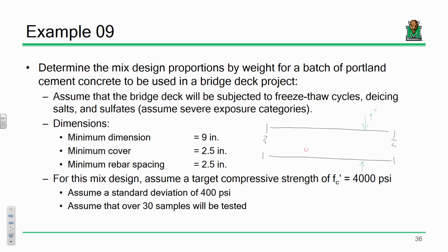Let's say I've got a piece of rebar right here. Cover is that distance, how far the piece of reinforcement is from the edge. Based on given applications, cover requirements can vary. For instance, cover requirements for interior elements are going to be different than cover requirements for exterior elements.